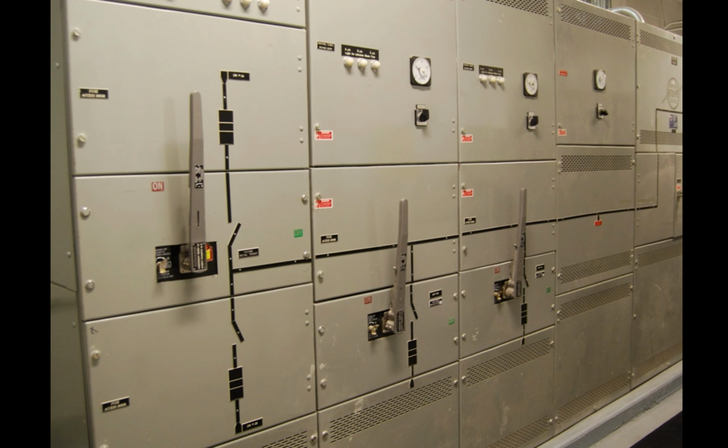And this is what a typical distribution room looks like, potentially in a basement or on the entry level. All of the higher electrical equipment is in there, switch gears, transformers, etc. And then you can monitor what kind of usage is going on there. If there are any major issues, there'll be panels in there which will light red or green to show you if there's a particular one that's not working. And then you see the main safety switch bars there, where if you want to work on something within it, you have to throw that switch down, which will shut the power to that particular piece of equipment.